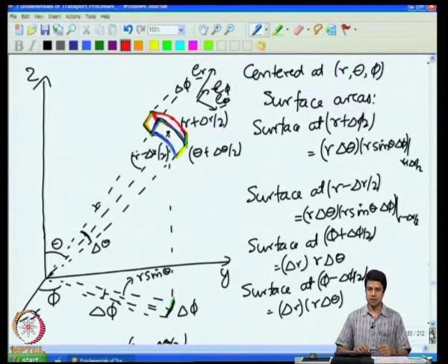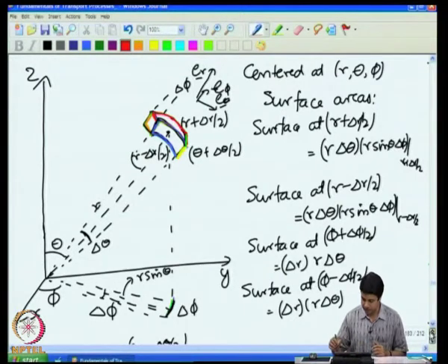And of course, the total change in mass within this differential volume is equal to the change in concentration within a time multiplied by the volume itself. This is equal to what comes in minus what goes out plus any sources or sinks. The amount of mass coming in or going out of these surfaces is equal to the flux times the surface area times the time interval. And so, all you need to know is what are the expressions for the surface area on each of these surfaces, and from that one can write down the flux balance.